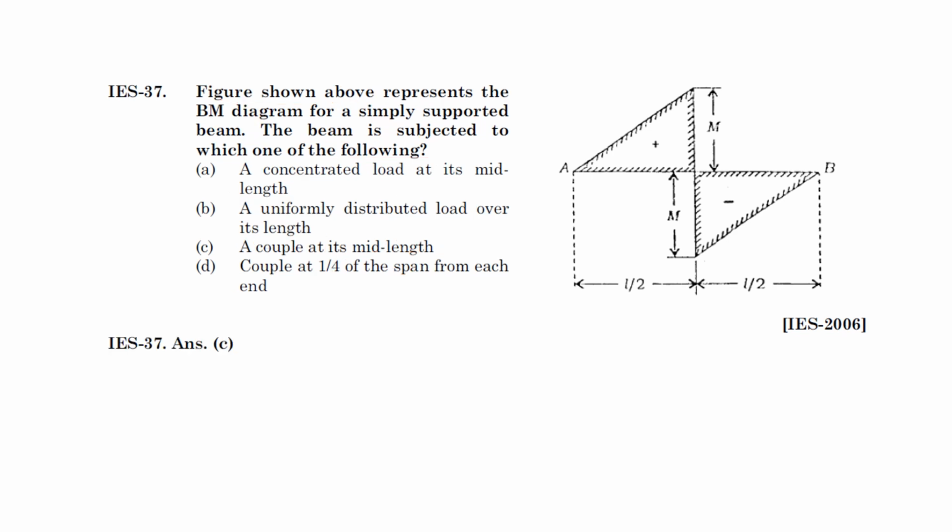In this bending condition, it is nothing but a couple at its mid length. You can see here M is given, so from here itself you can get a clue. This will be a couple. So a couple at its mid span. So the answer is C.